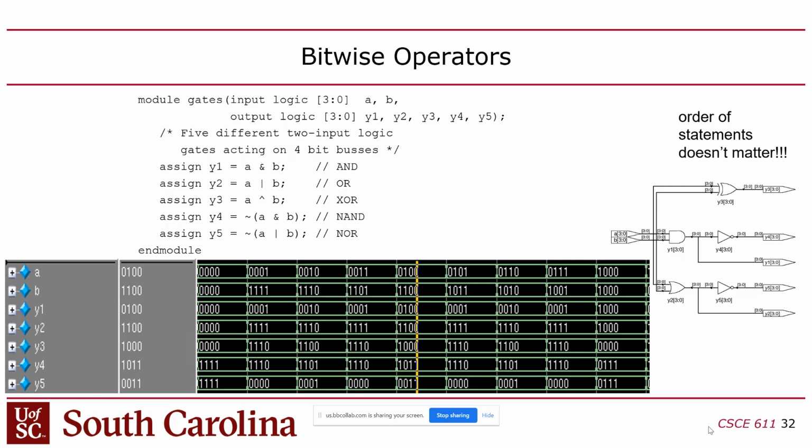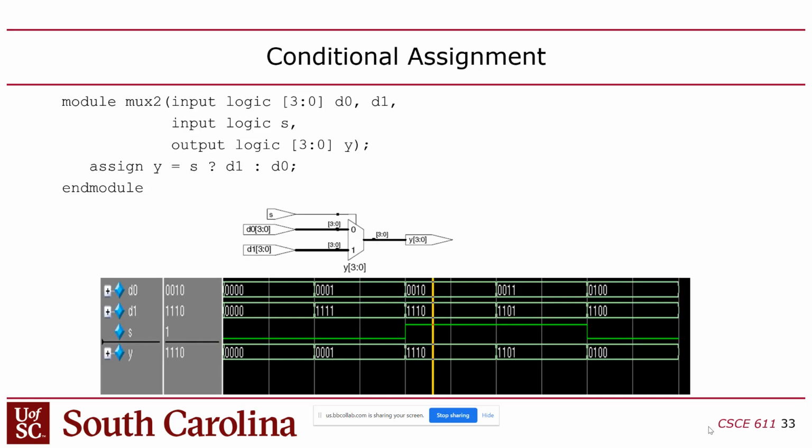That's the point. Okay, so then there's something else I want to show you that you've got in Java and C. It's the ternary statement. It's this question mark syntax. I don't know if you guys ever use this. In my opinion, it's not as commonly used in C as it is in Verilog. In Verilog, it's used a lot. Not because people are trying to be fancy, but because it's a very natural way to create a multiplexer. So even though you can do this in C and Java, basically no one uses it.